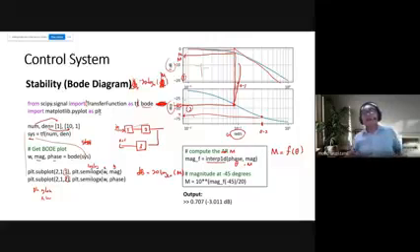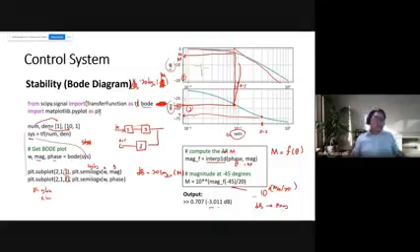This is the code to convert the magnitude in dB to magnitude. So in dB you get something like this, negative 3. So this is 10 power, in this case 10 power of your magnitude in dB divided by 20. So that is the conversion from dB to magnitude. Right. Okay. So next.